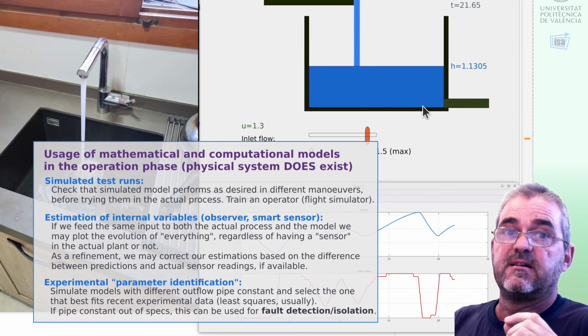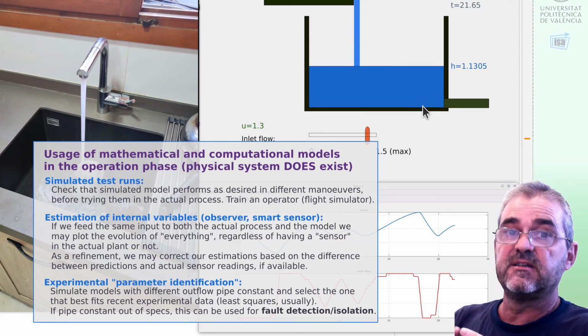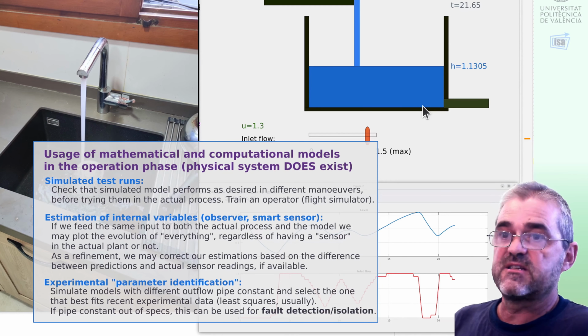And there is a more advanced methodology, which is called observer, in which I feed not only the inputs, but whatever physical sensors of levels, pressures, flows, or whatever I have in my system.